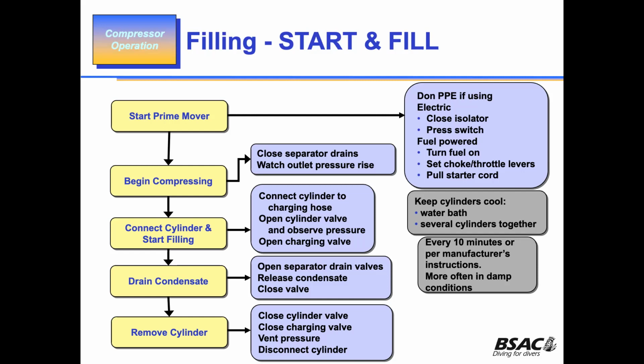It sits in the bottom of the separator, and you just blow that out, because as the water level goes up, you've got more risk of liquid carryover between cylinders, and you don't want that. Does that answer your question? But you won't fill the cylinder. At the end of the day, it will take forever. And I know, because I've done it. I'm talking from experience.